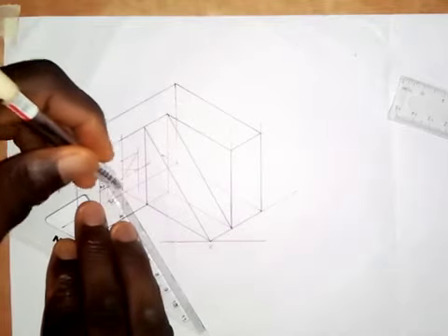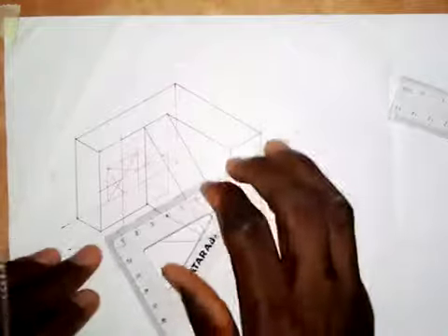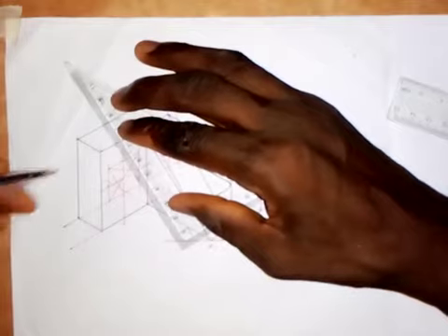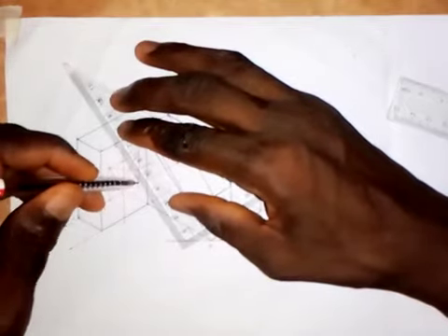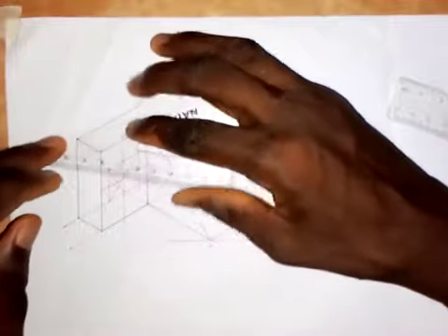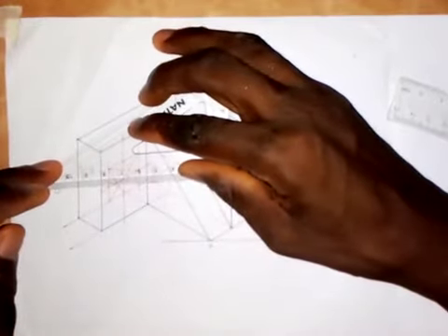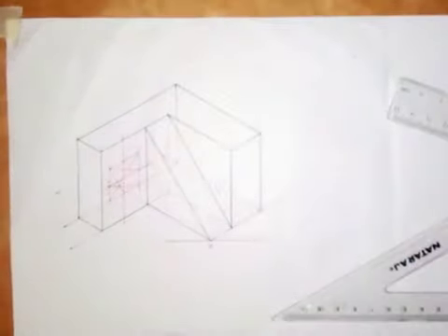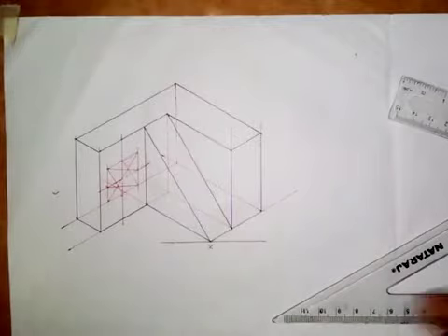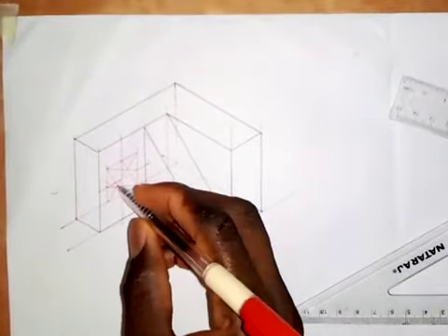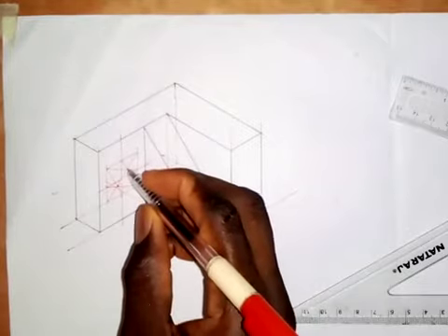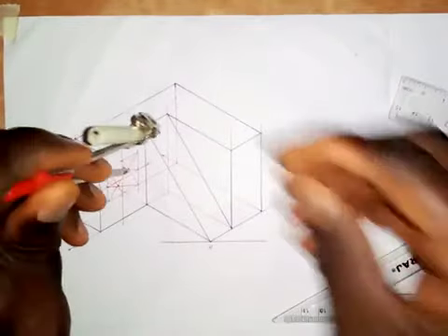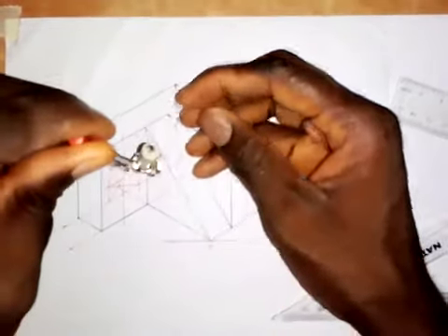So for those who have watched my videos, you should have seen the way I did the construction of the isometric circle. So what we are trying to do is to draw an isometric circle. An isometric circle is not a normal circle, it's an ellipse. It's always an ellipse. So with the points that we have gotten, the next thing we are going to do is the four center method. We are going to make use of this point, this point, this point, and this point to get the isometric circle. So I put the pinpoint on my compass here and I will draw this.